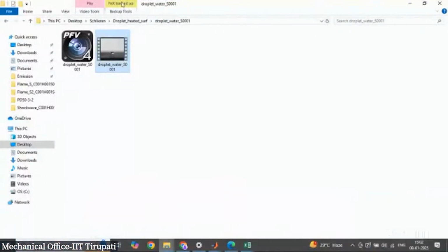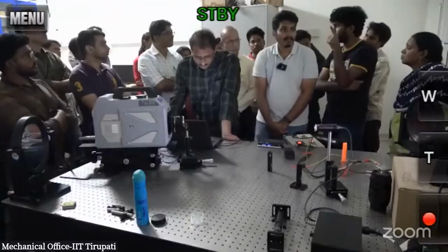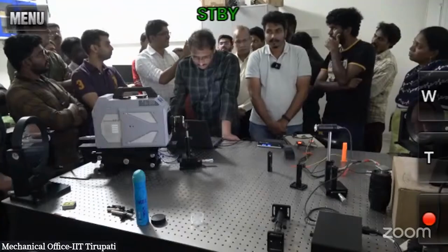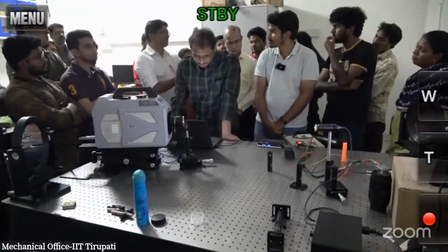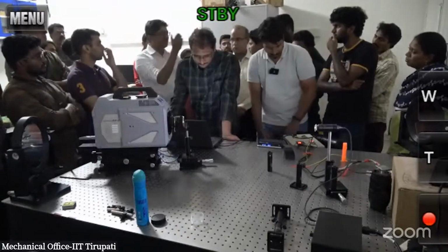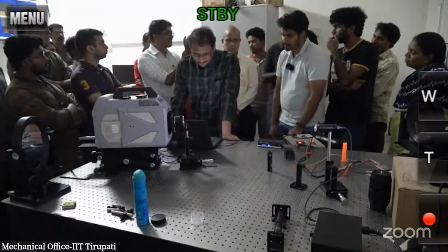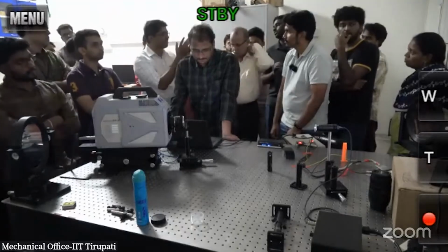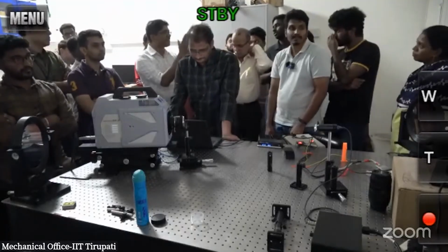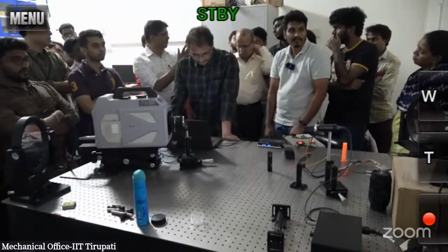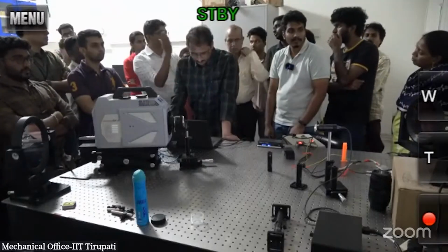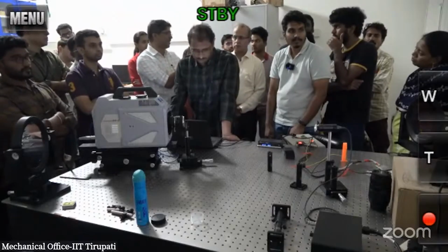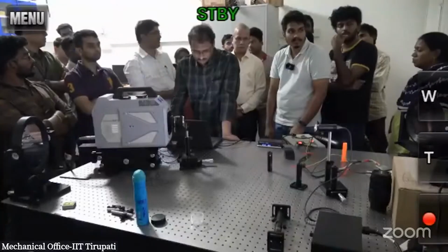Are there any fuels for which the flame front can travel upstream? Right now we see the flow velocity. You have a flame here. The flame doesn't know which direction it is traveling. If you supply continuously, and the flame velocity matches the incoming velocity, the flame will stay at one position. If it is more, it will go like this. If it is slower, it will go backward.